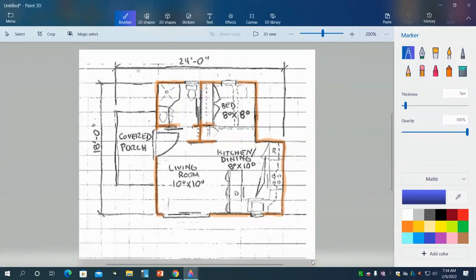So I want to help you do those. Because what we need to do at this point is make sure that we can design a roof that's going to clear all of the water off the roof. A lot of times, the first time people do this, they start drawing in different lines and different planes, and they end up pitching water back into the building or not having water clear off the building, and we run into a big problem.